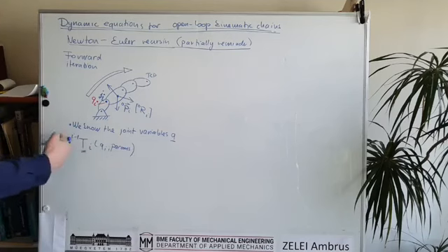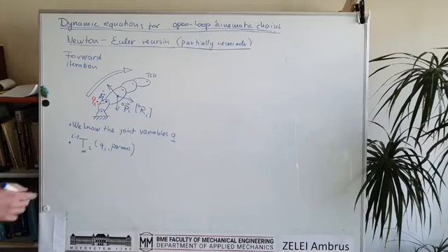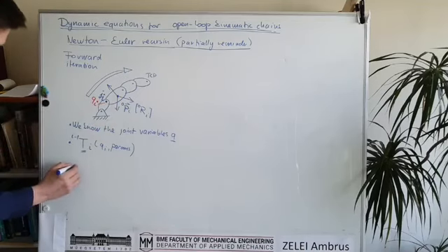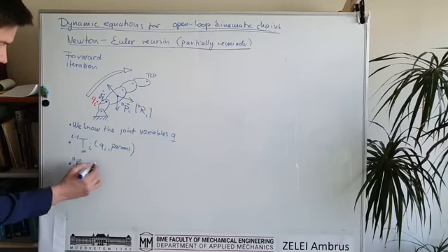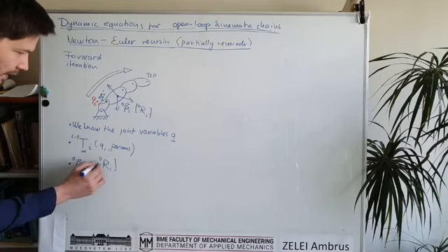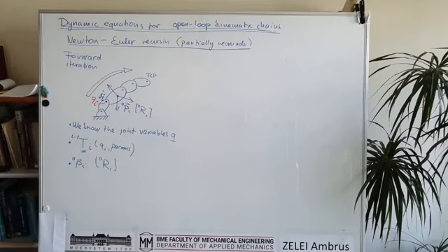So we can always calculate these homogeneous transformation matrices, and then by using the neighboring homogeneous transformation matrices we can obtain the position of each link in the global frame and the orientation of each link in the global frame. So that's what we do.